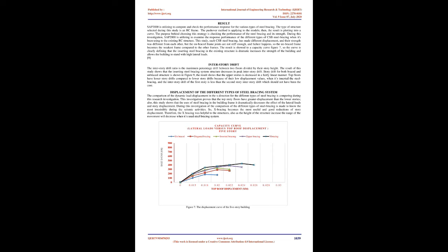Steel bracing system. The function of the steel bracing is to protect the structure under earthquake loading. Also, the steel bracing system increases the strength of the RC building. After more research and application, this idea has become more relevant for seismic protection because of the simplicity of implementation, and it is relatively cheaper than the shear wall.